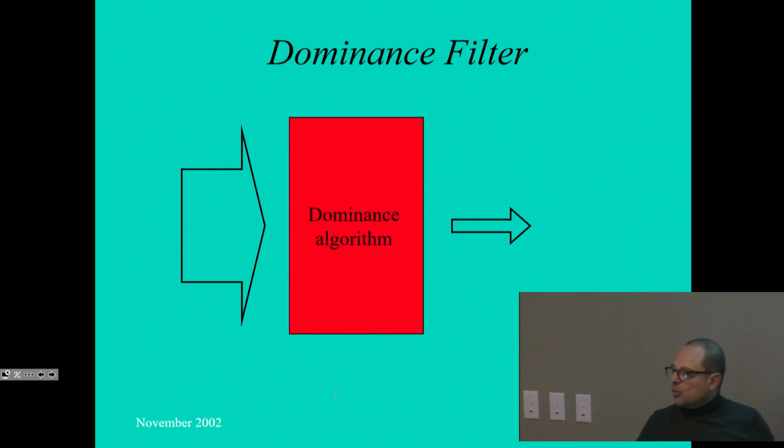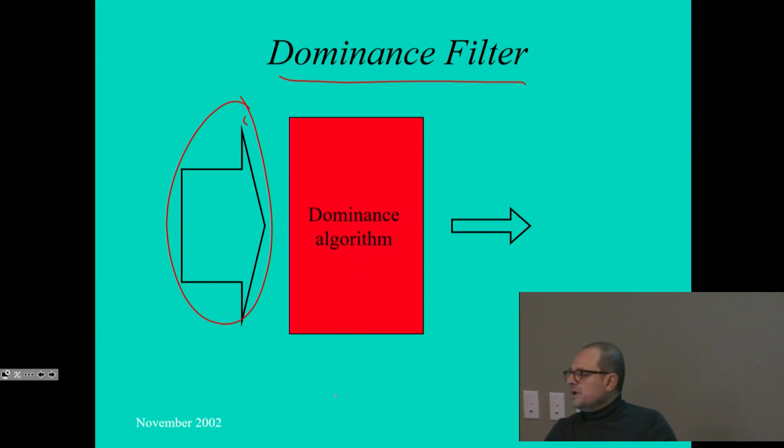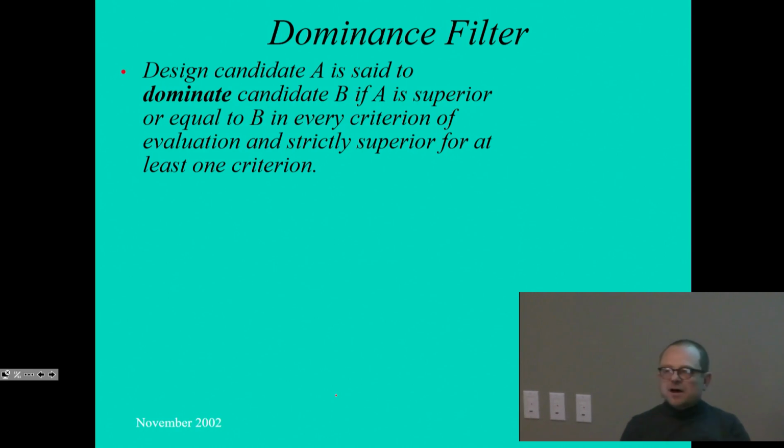So that was fine. So we created a super large set now of results, because for every simulation, we have so many different instances of driving cycles. So now, we suggested the idea of a dominance filter that would greatly reduce our output space. What's a dominance filter? The dominance filter says the following. If I have a design candidate A, and in every performance index, this design candidate A is better than design candidate B, then why would you keep B?